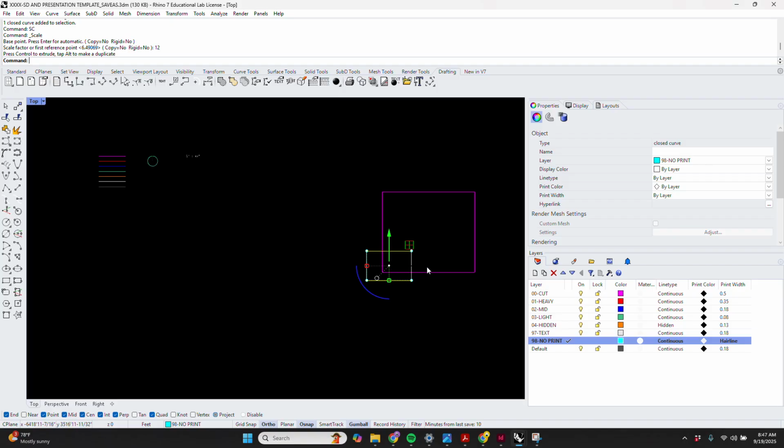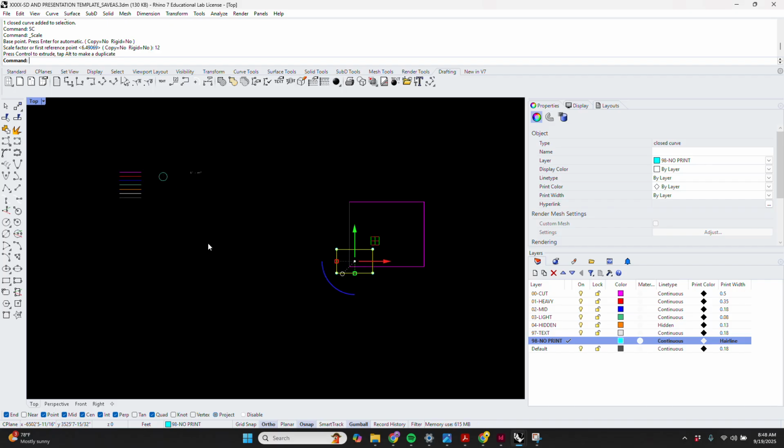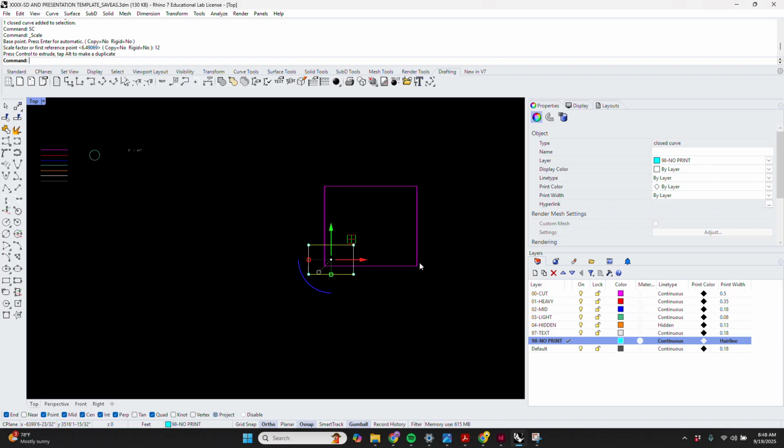When you're working in Imperial, the way I like to think about it, I always multiply it by 12 off the bat. So it's kind of 1 inch to 1 foot. And then whatever you multiply it, kind of scale it by next, is the denominator of your scale. So some common ones, these are round numbers. This is like a common one. The two that I'm like, I don't know exactly which it will be.